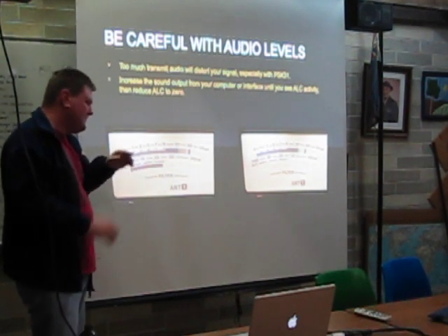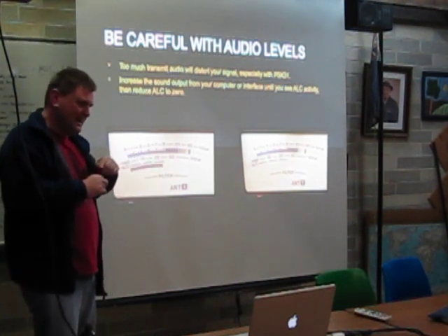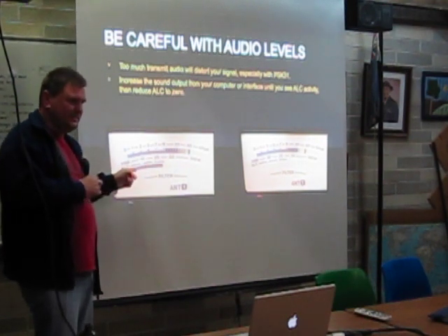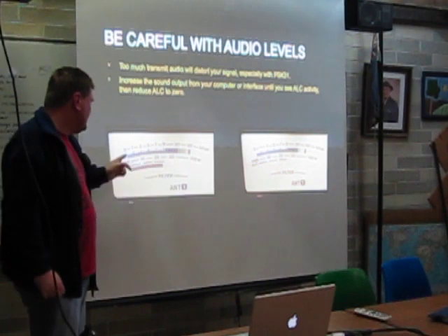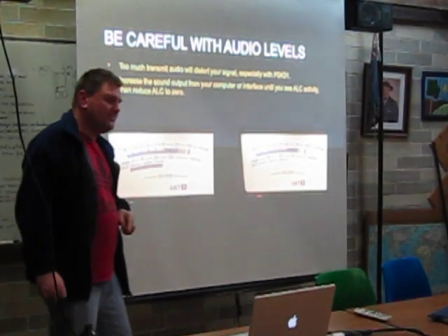And so whenever you wind back the gain of the transmitter, you're now affecting the linearity. So having ALC indication is usually very bad, especially for modes like PSK. So whenever you do digital modes, you generally want to make sure you have no ALC action.